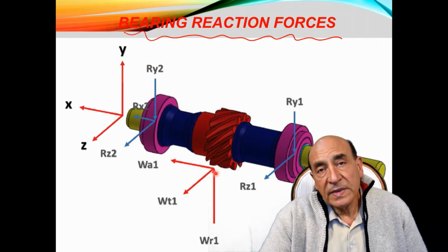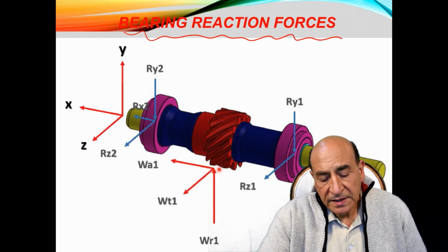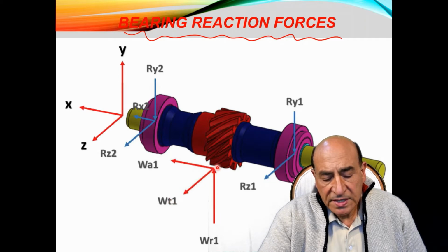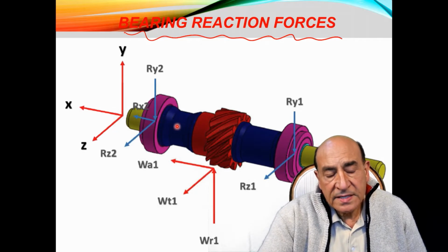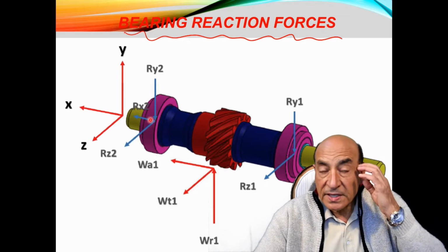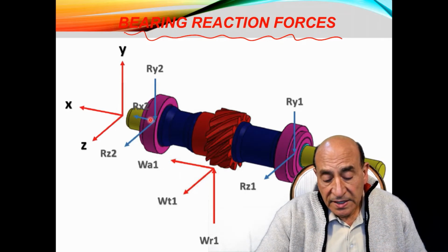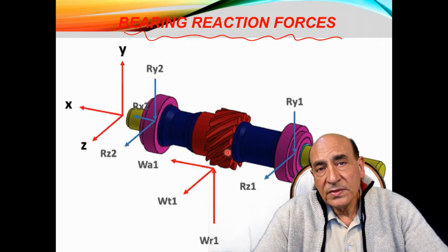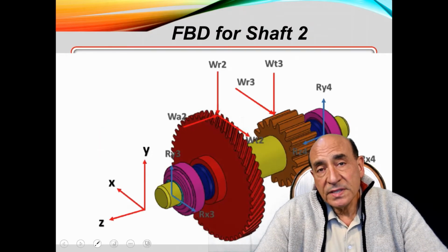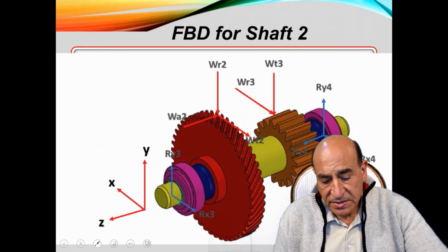The interesting part about the helical gear is that at the contact point with the other gear, it will have a radial component of the force, a tangential component of the force, and an axial component. This axial component has to be taken by a retaining ring so that the gear doesn't slide out of the shaft, and the radial component is going to cause the bending of the gear teeth. So we have to design the gear teeth for that bending stress.